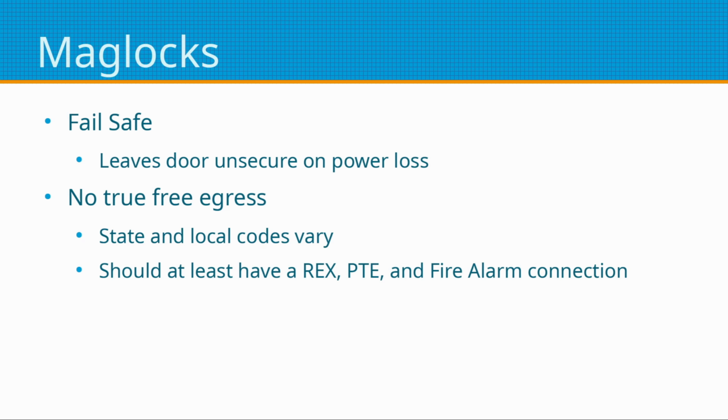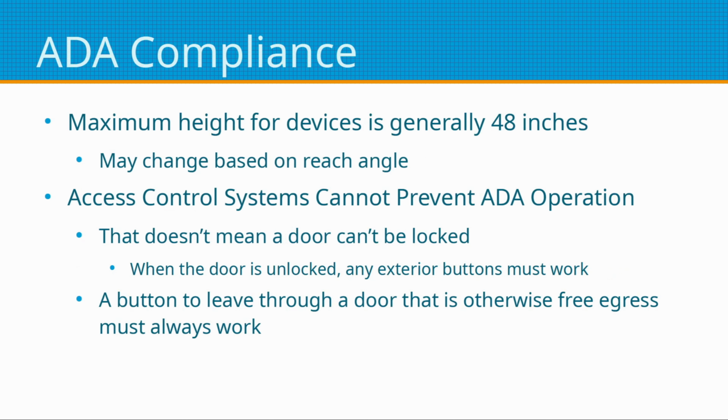You'll also see what's sometimes called a shear lock. Instead of the lock I just showed you where the two faces hit when the door closes, a shear lock is actually in the top jamb of the frame and the plate is in the top of the door, and it pulls the plate up to the top of the frame. Those are common in doors that are all glass that don't have enough room to adhere a plate to the side.